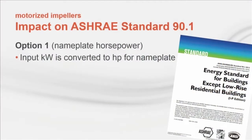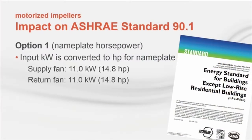In our previous example, the input power to the supply fan array was 11 kW and also 11 kW to the return fan array. So the total horsepower on the nameplate would be 14.8 for each array. Keep in mind that this value includes variable speed drive and motor losses, so you might have a higher nameplate horsepower when using a motorized impeller compared to a traditional direct drive plenum fan. However, it could be lower if the direct drive plenum fan had to jump up to the next higher NEMA horsepower increment, from 7.5 to 10 horsepower, for example.